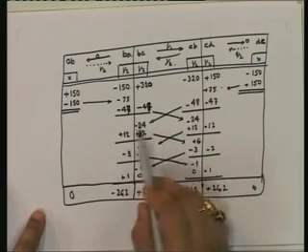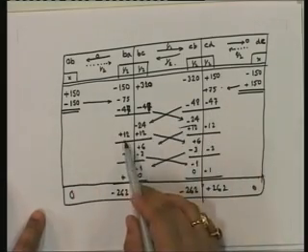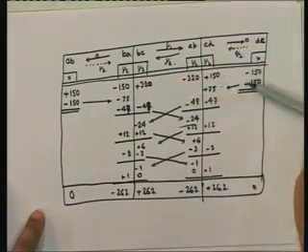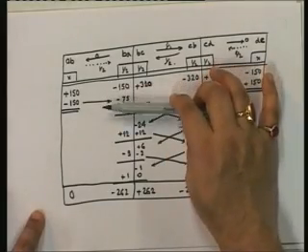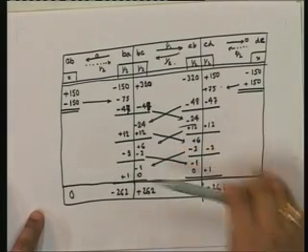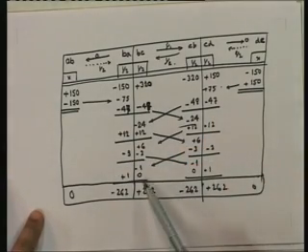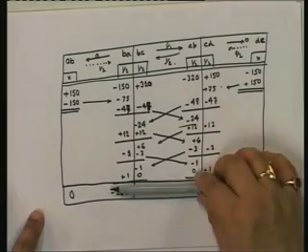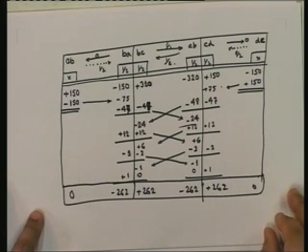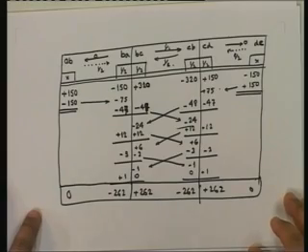Then once we have finished the carryover, we look at all the unbalanced moments and do the distribution. So you have fixed end moments, then the modified member carryovers, then distribution, carryover, distribution, carryover, distribution, carryover, distribution, till we hit a situation where the carryover is 0, and so ultimately the distribution is ended, and that is your final member force. Okay? So this in essence is your overall moment distribution method as we see it for beams.